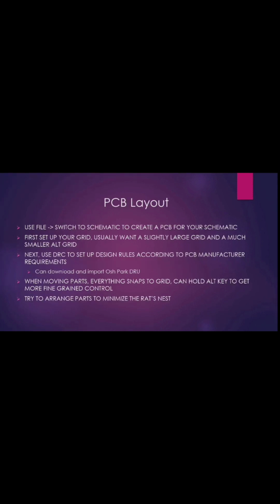The next session might be the layout session. Click File and select Switch to Board to create a PCB for your circuit diagram. Now create a grid which is slightly larger and a grid which is much smaller using Alt grid. Then use the diagnose tool to find the errors with respect to the designer's requirements.